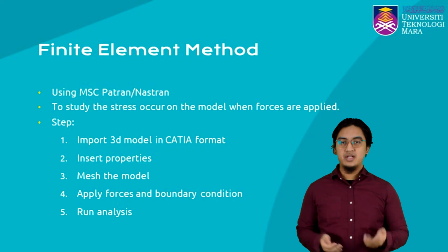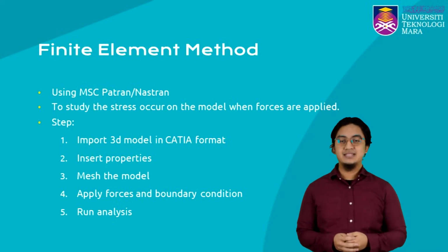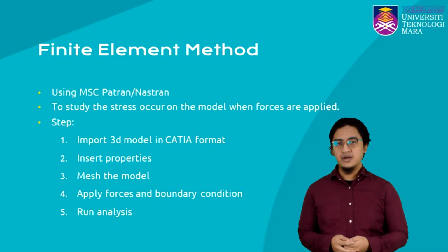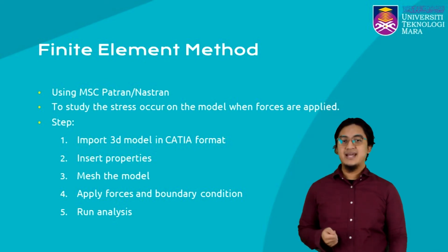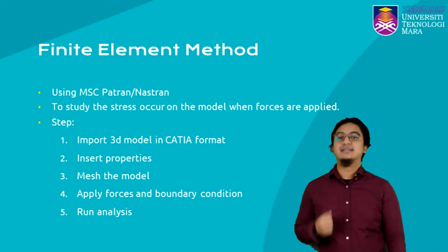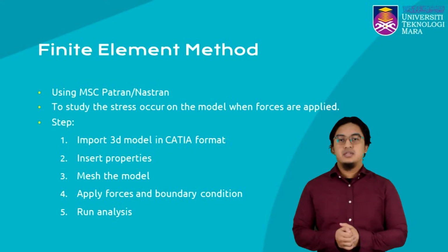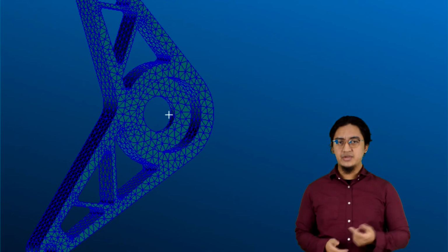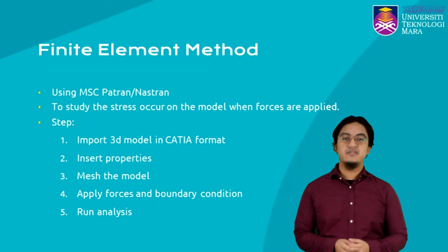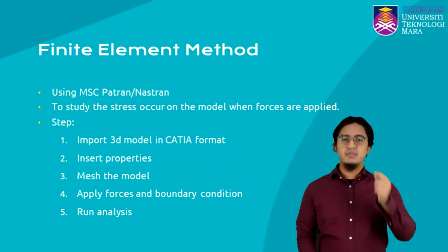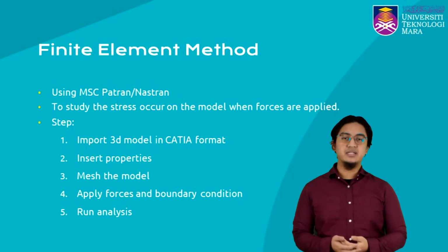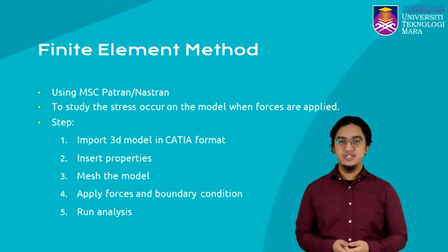Like I said before, the material used for the mounting is 7075-T651 aluminum alloy, and the model was set as solid. Then, mesh the model. Theoretically, the smaller the mesh size, the more accurate the result. Since I'm using the student version of the software, the number of elements and nodes is limited. Thus, the mesh size used is 5 mm.